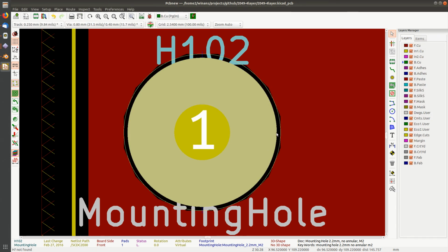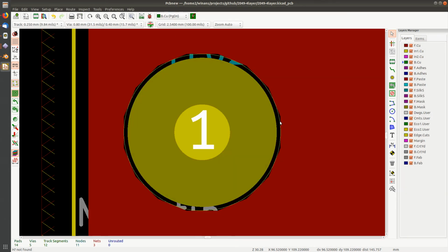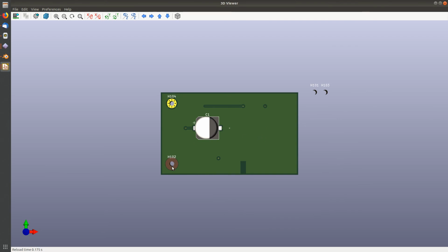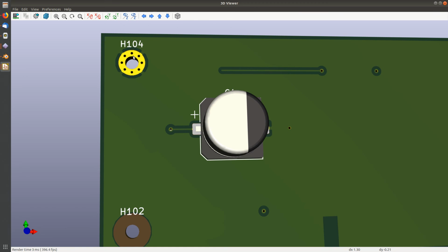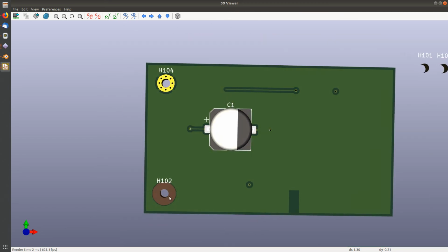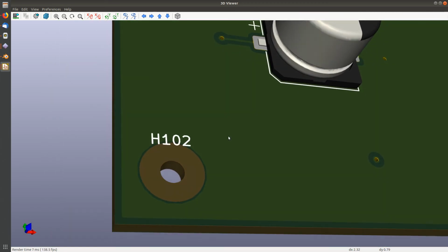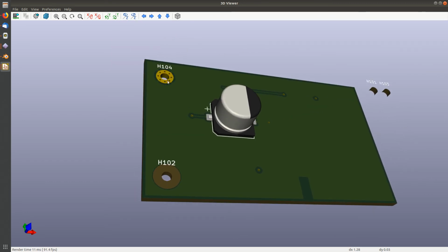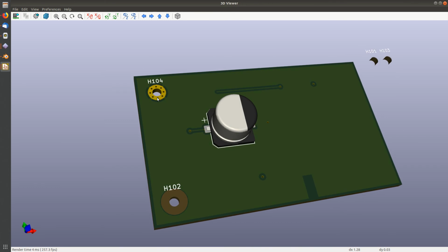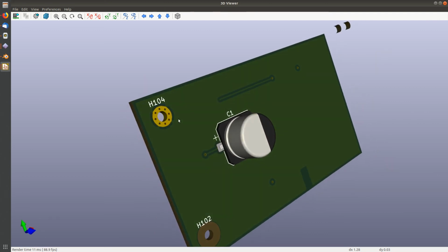leeway. I just hit B to report the polygons, so that this here is 0.15 millimeters of overlap there. A little bit of overlap like I talked about before. So you got your plated, you got your non-plated. The last thing about the non-plated is that not all manufacturers can do non-plated holes. You'd think that you'd have the problem with plated through holes. Some manufacturers cannot do this, okay? If you run into that situation, you have to make all of them plated.